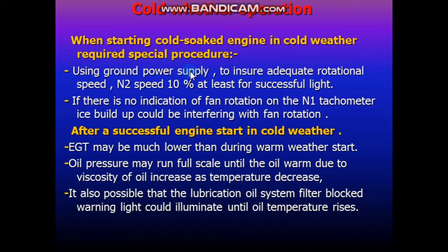Why? To make adequate or the appropriate rotational speed, and the N2 must exceed 10% at least. And if N1 didn't rotate or didn't give us indication, that means there is ice build-up on the N1, and you have to open the anti-ice system to make it rotate again.